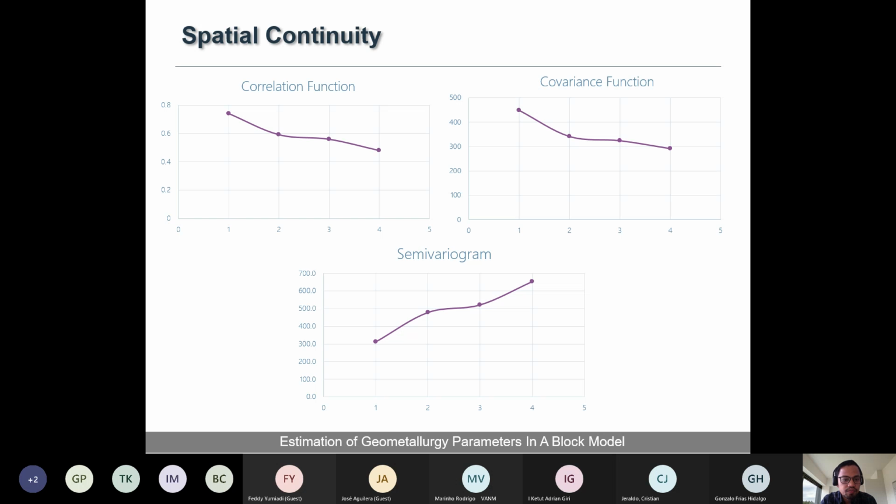So in this case, if we put zero distance, the result of the semi-variogram will be 0, right? But in a real case, we don't use a specific direction. I mean, not an absolute direction, not exactly 1 meter. We use a tolerance, right? Like a searching tolerance of 20 degrees or 30 degrees from our direction of interest. So in that sense, the nugget effect will appear, caused by sampling error and short scale variability.